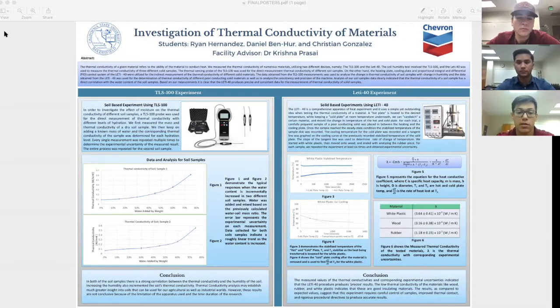The secondary apparatus has 2 plates along with a fan. The fan is used when recording the temperature when the cold plate is cooling. The main apparatus was used in measuring the temperature of the 2 plates. To control the temperature of the 2 plates, there is a manual knob and a proportional integral and differential system, or PID system. The PID system changes the temperature of the plates to stabilize the temperature between them. The system heats the plate above and cools the plate below without having to use the manual temperature knob to stabilize the 2. We used the PID system to ensure we had a consistent starting temperature for all trials of each material.